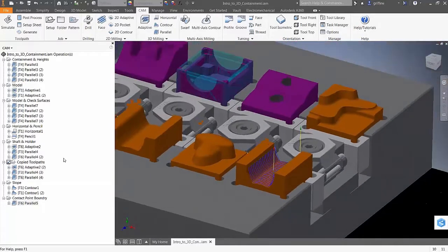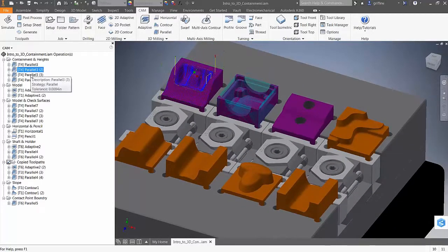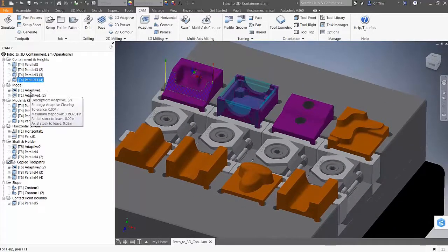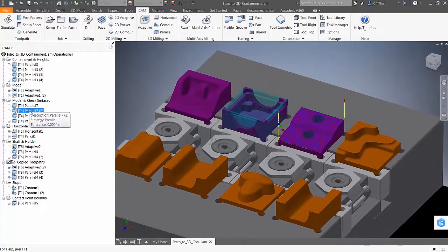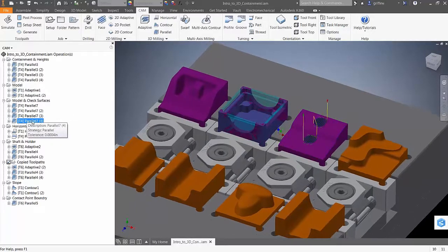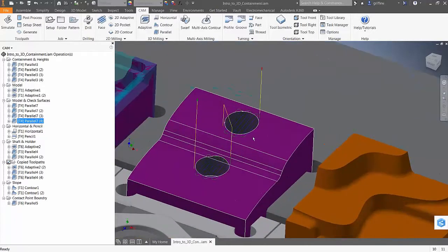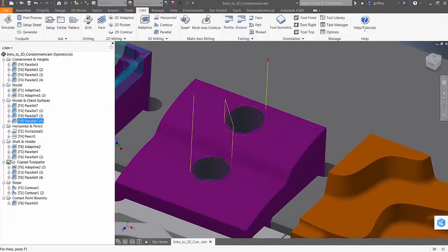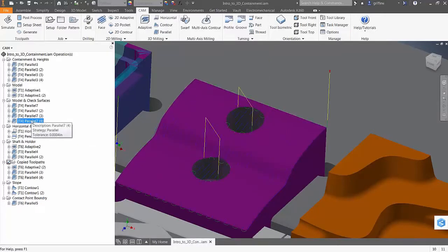So we've looked at a lot of different ways we can contain the toolpaths. Okay, we select geometry. Model override is another way to work with it. Using model override we can avoid holes using surfaces. Also touch surfaces we can work with to contain the toolpath within a surface region, and also to let you know you don't have to have surfaces drawn. You can select any region on the part and use that as a driven surface where you can contain your toolpath.